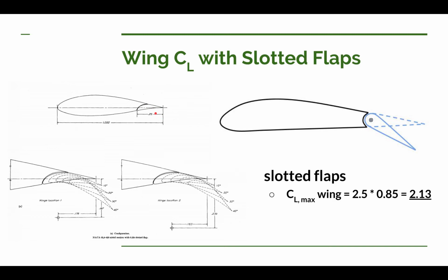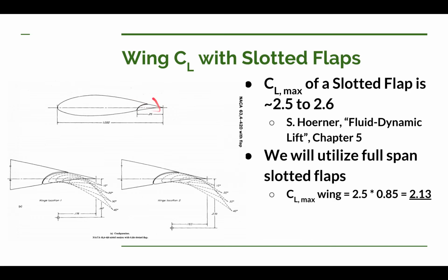And in addition, if you have unsealed flaps, you have an even worse situation. You've got a gap here between the wing and the leading edge, and instead of the air shooting out right along the surface of the flap, it actually shoots almost straight out. That's even worse because it further disrupts this boundary layer and increases the drag even more because your boundary layer is separating even worse. So the slotted flap has a potential for significantly less drag for increased lift compared to the plane flap.